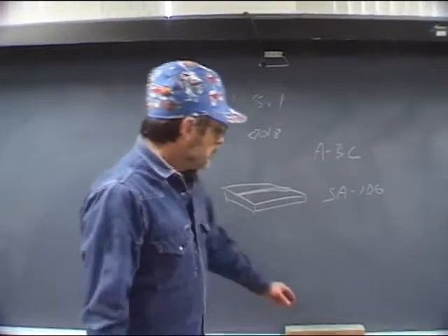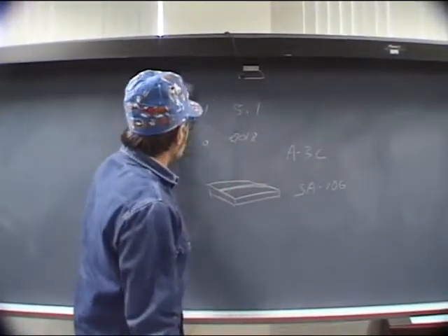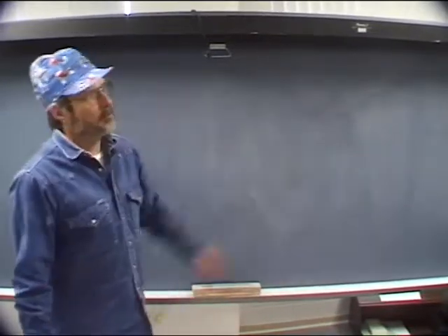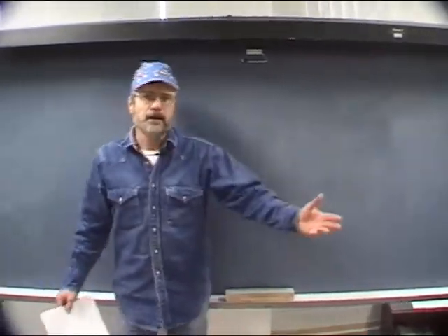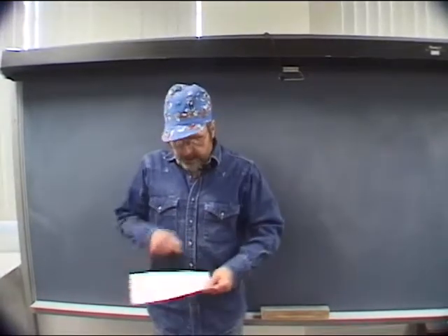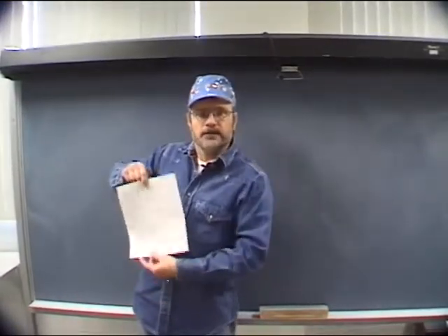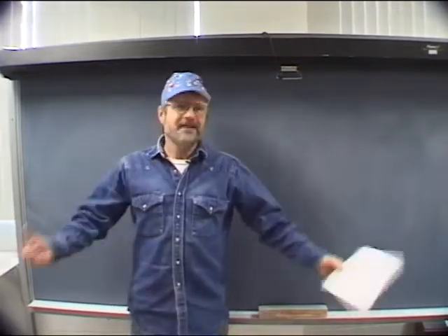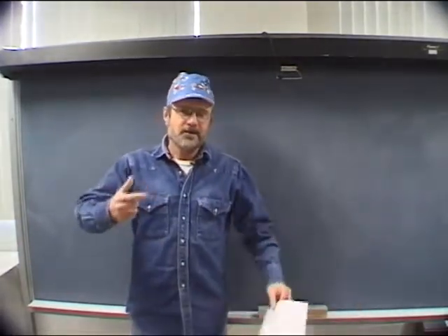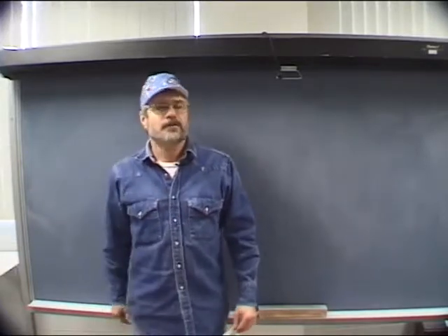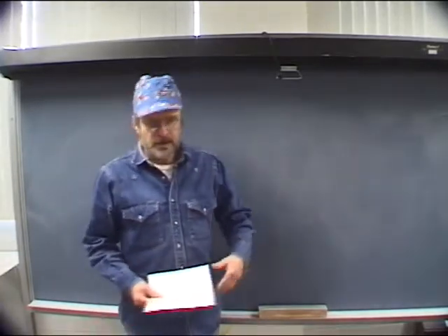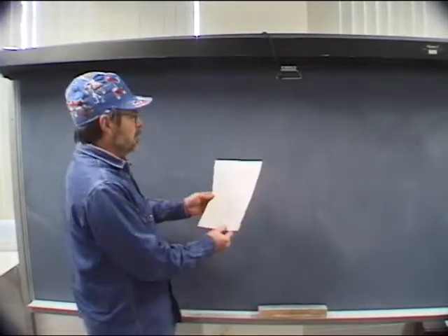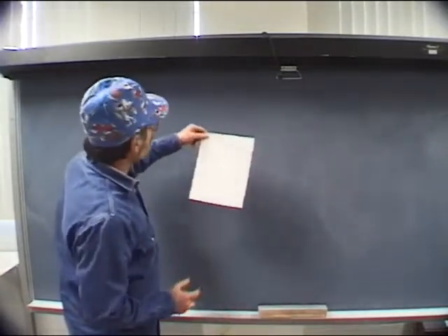Under D11, if you're going to do a welding procedure, you have to qualify that procedure in every position. If we want to do a plate procedure under AWS, we would have to do a test in the flat position, a test in the vertical position, a test in the horizontal position, and a test in the overhead position. So the code's different. But always make sure that you're working to the code that the work's going to be done under, because they all change. It's their little kingdom, and they want to be God in that kingdom. So you have to follow whatever it says in those codes.